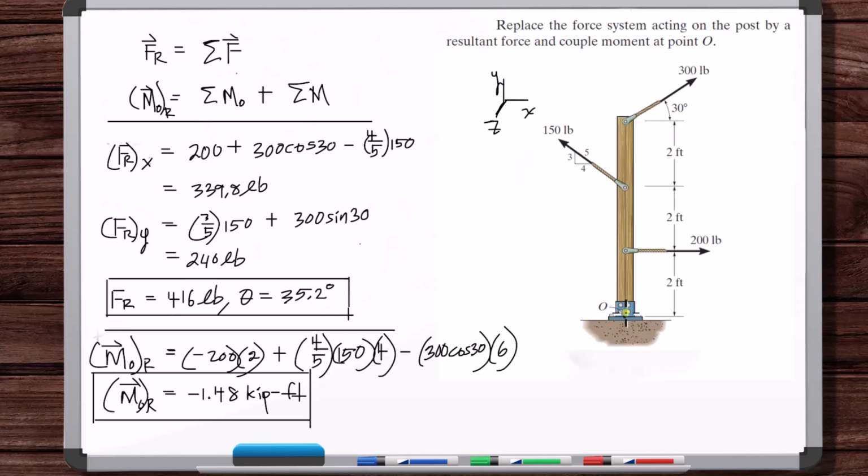So you've got a resultant force like here, and then a moment clockwise here. And remember what this means. The idea is, as shown here, this is not an equivalent system to what it was originally when we started this problem. Now it's an equivalent system. It's statically equivalent.